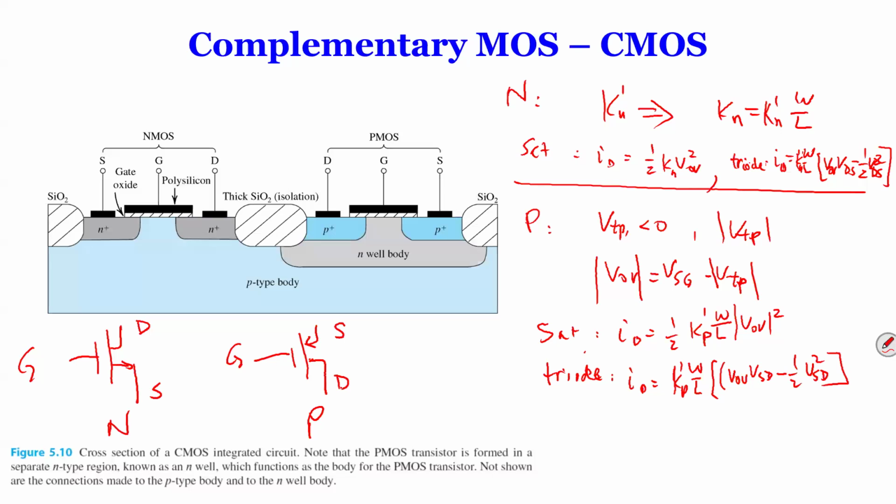Another thing I want to remind you is that because the MOSFET is symmetrical, the source and drain actually are reversible. So even though we have a current in this direction, you actually can reverse this, use this as a drain, this as a source, and current will flow in this direction. There's nothing wrong with it. So MOSFET is always like that. But in future applications, you actually see this.